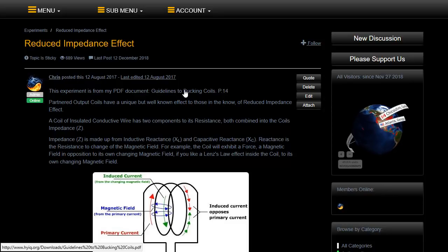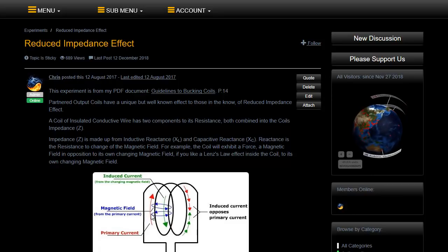Now, as it starts off going slow, the current draw will be very high. As the motor speeds up, the current draw will reduce. So the current is actually coming down as the motor spins faster. And that's the back EMF in the coils. The back EMF basically creates a larger resistance in the coils because the magnetic field is changing faster within the coils.